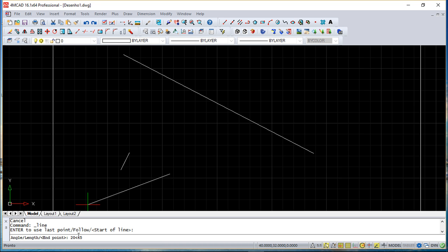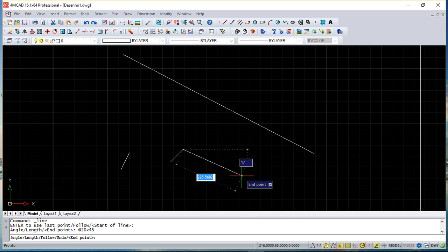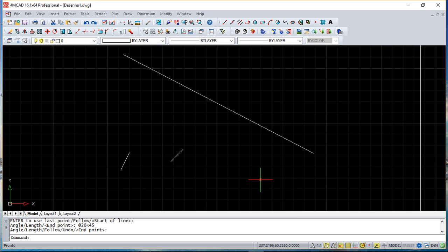And if I use this notation, it's again regarding the origin. If I say before I put this kind of thing here, then it is relative to the last point. Okay, let us use a practical example. So for example, one point here, and I can say the at, and now 20 in the size of the vector, and the angle will be 45. Okay, something like that. It's very easy.